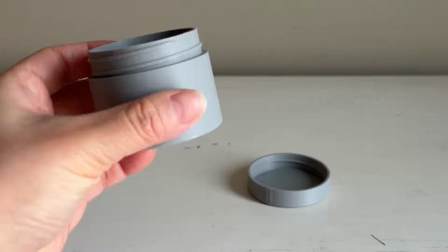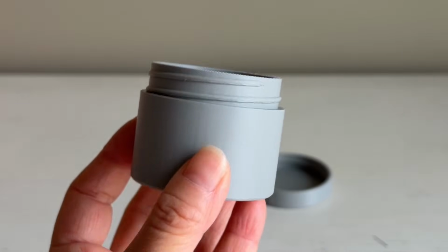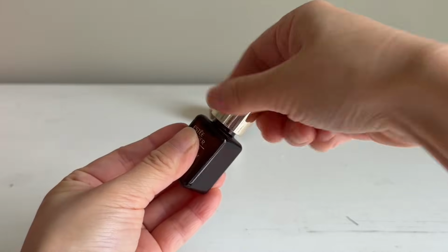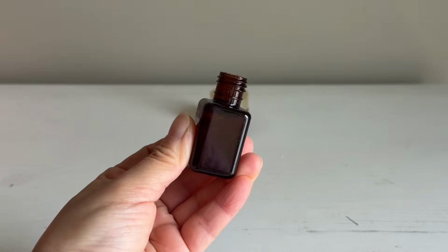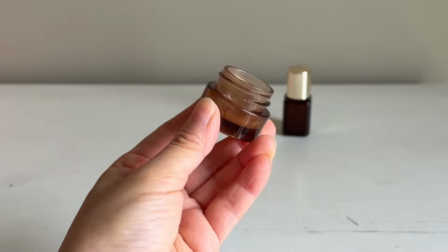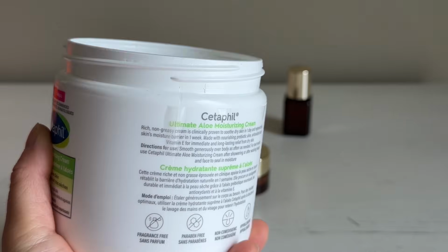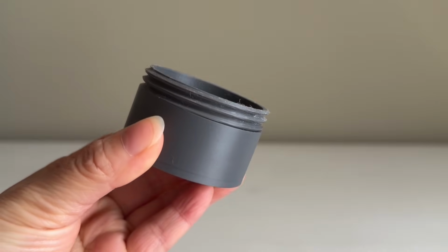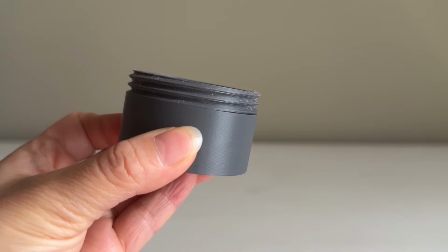In this video, we're going to show you how to model a threaded bottle using the Coil tool in Fusion 360. First, let's take a look at these everyday plastic bottles. Notice the threading here. It has a wide pitch and very few turns. Same with this one, and it's more obvious on this one, right? These real-world bottles are quite different from the ones we created using the thread tool in our last video.